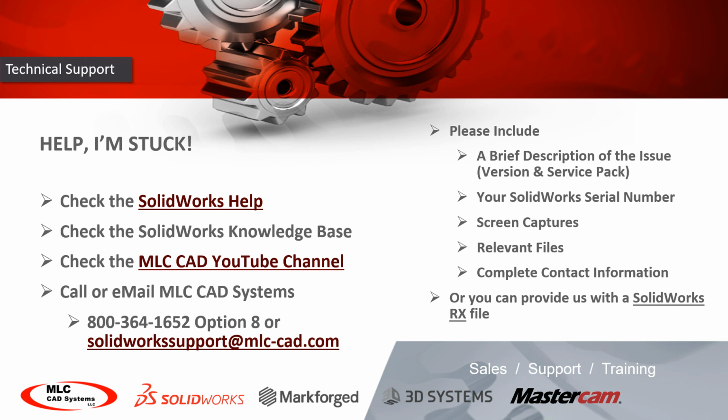I do want to mention that SolidWorks RX program one more time. That's installed automatically with SolidWorks. It's where I recommended checking the Diagnostics tab. It has a function called Problem Capture. Using this, you can record your SolidWorks screen, what clicks you're making, even include files if you want to, and zip that up into one little file. When you send that to us, it gives us log file information, it gives us a recording, we can start troubleshooting and researching on our end. It basically encapsulates 100% of the problem, so when we get back to you, we have the best possible information.